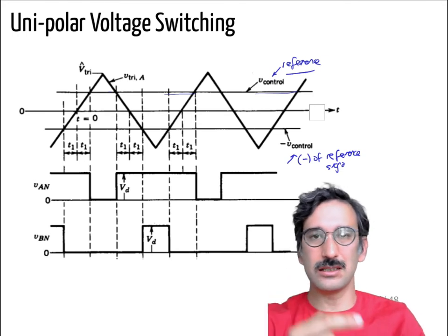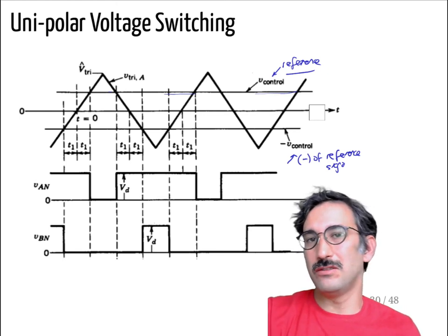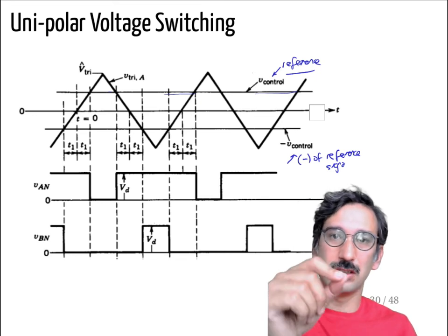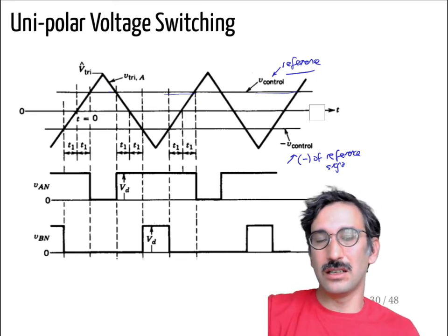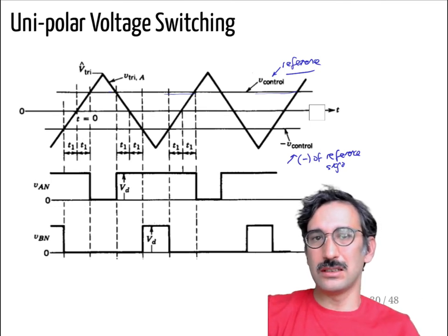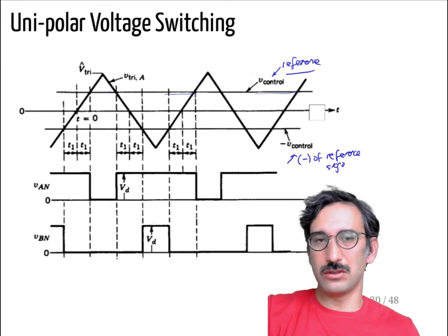So you generate some, I don't know, you can use a voltage division circuit, another op-amp circuit, or maybe you have a potentiometer where you can adjust the voltage level, that kind of thing. So you can generate that voltage, but you are not drawing current from that voltage level.